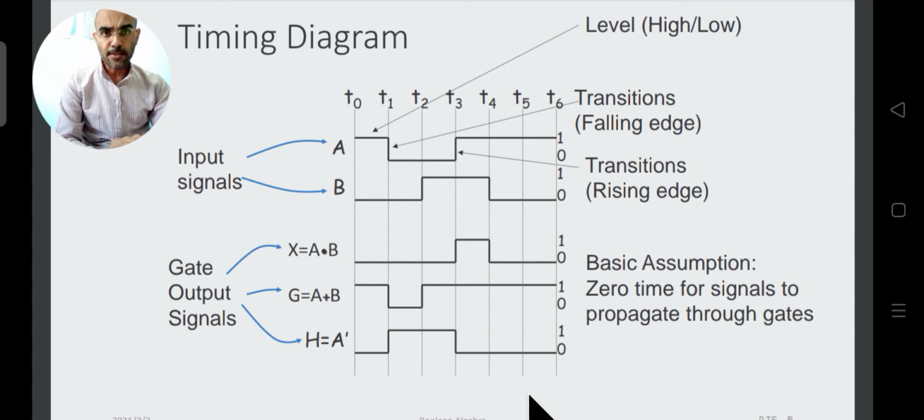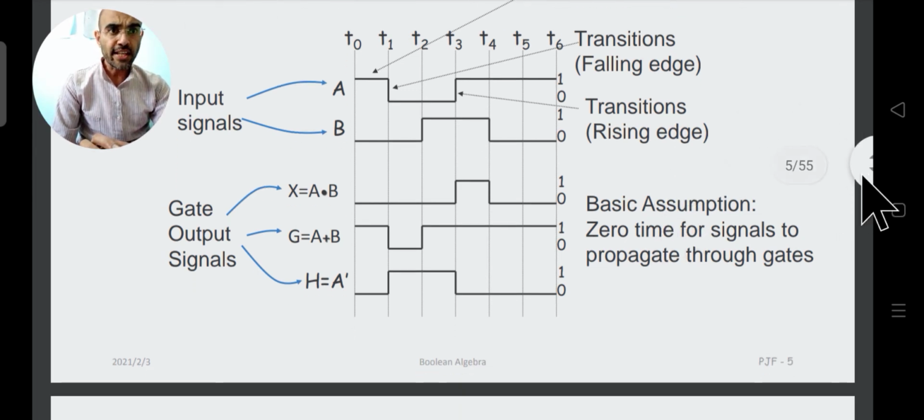So this is a simple timing diagram for any gate. But if you understand this logic well, then you can use the same logic to show the timing diagram of any waveform, of any output, whether it is a counter or any function. And this is useful in your competitive exams as well, because sometimes rather than giving the combinations of the truth table, they show it with the help of a timing diagram. So we should be able to understand this as well, okay. Moving on to the next slide.